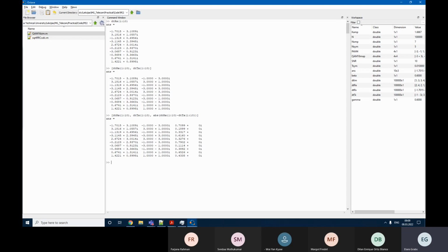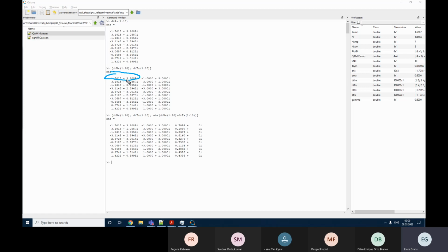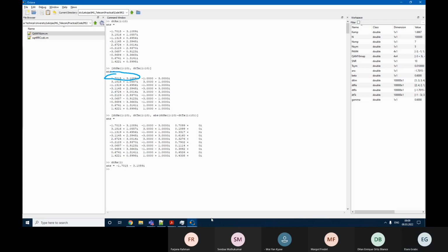So what we actually need to do now is to calculate for this point the distance to each of the 16 original constellation points. So what I'm going to do now is to take this first value, data Rx1, then find the difference for all this map. Basically data Rx first minus QAM-16 map, and also absolute value, of course.